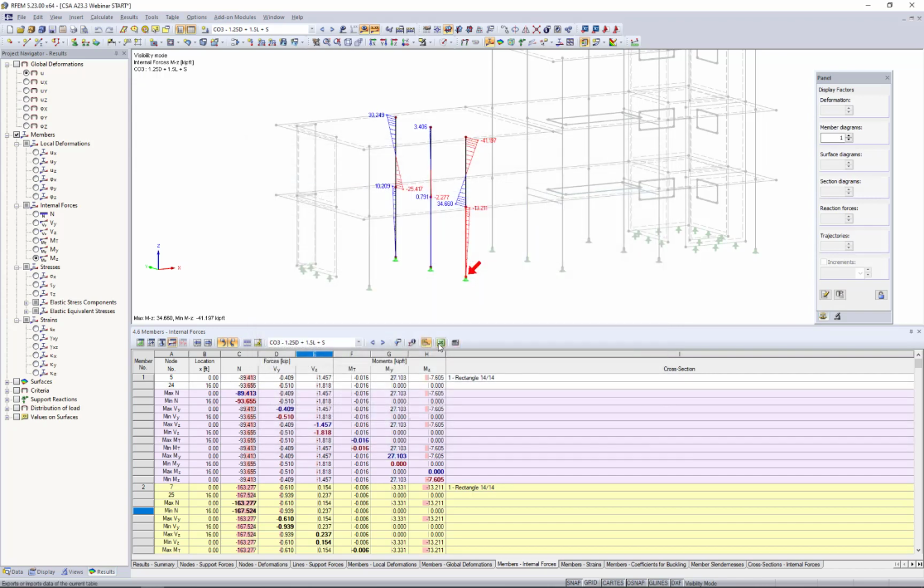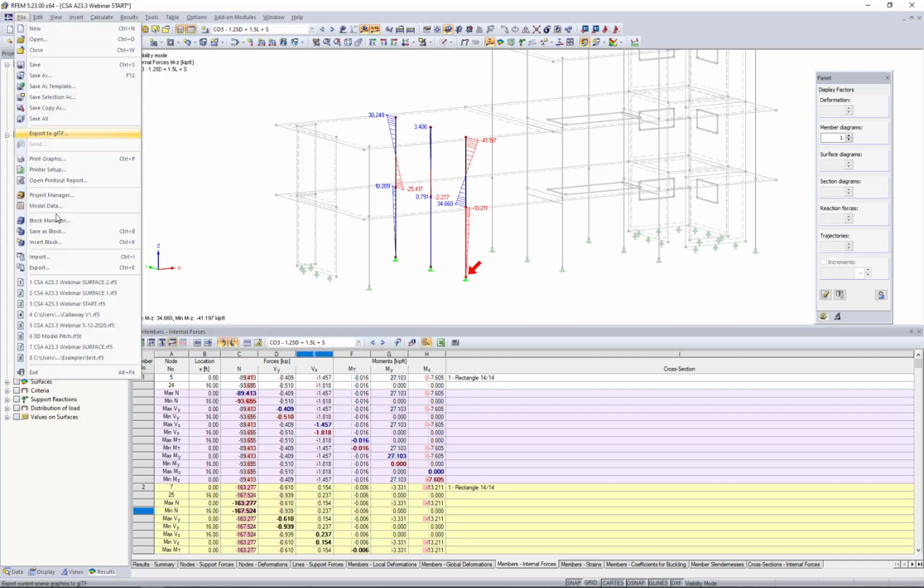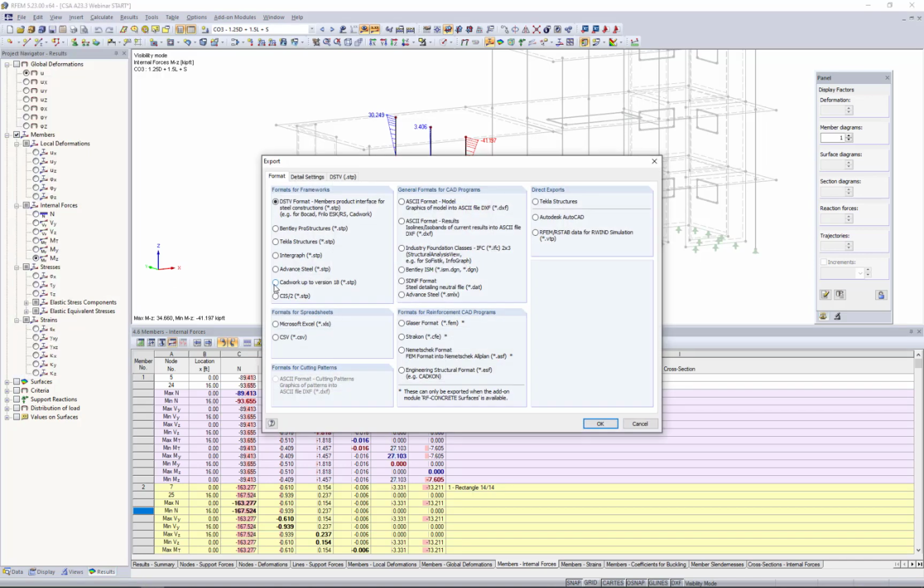We can export these internal forces directly to Microsoft Excel. So this would consider the current table and the current load combination, just give you a quick export. This might be important for doing a hand calculation or manual design for the reinforcement. Now in turn, under File, Export, we also have the ability here to export as a Microsoft Excel XLS file.